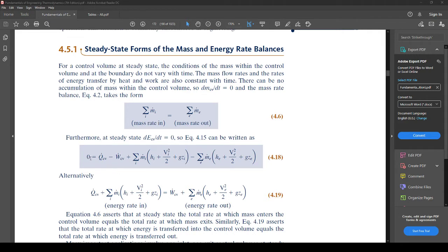That goes to 0, and Q of the control volume and work of the control volume are added, all this equals the summation of the energy of the inlet and the summation of the energy of the outlet. And when I say energy, I mean all types: work of the fluid, velocity, which is kinetic energy, and potential, right? So the energy forms that we care about.